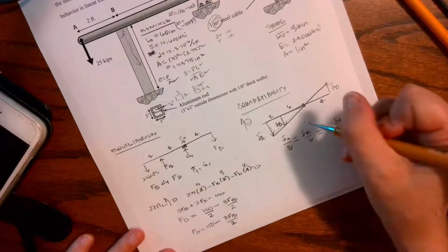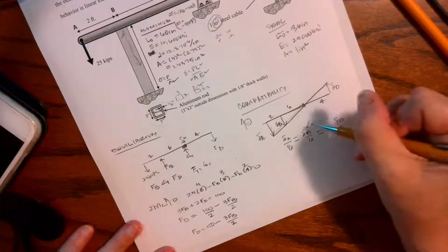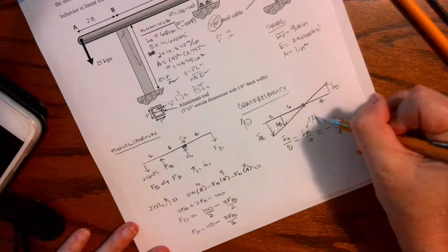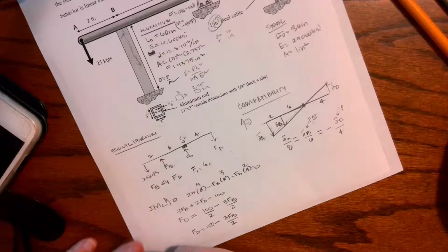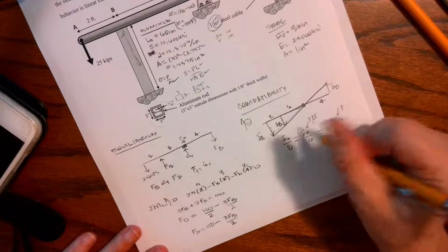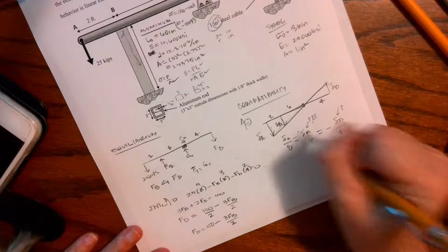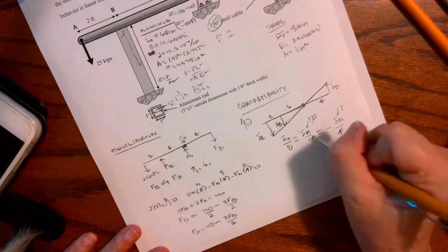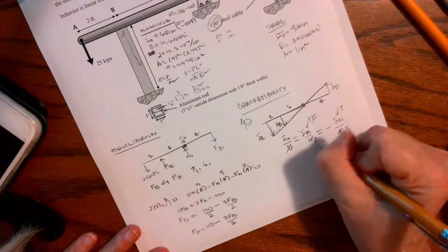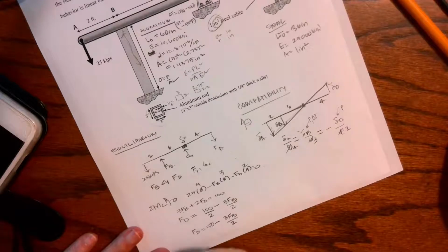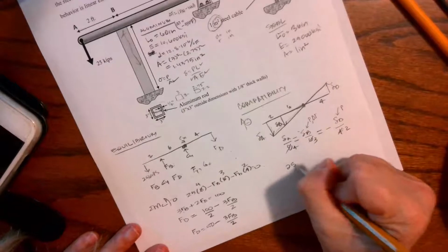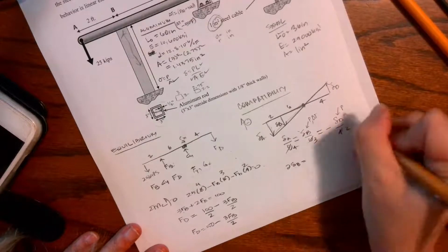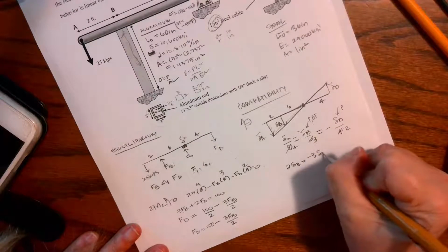When I know about deltas, it's a function of force and temperature change. We have force and temperature change on B, and we just have force on D. So I can start simplifying, and I can say, let's just get rid of a 2 here. So I've got a 2 and a 3 and a 4. Might as well, smaller numbers. So I have 2 delta B equals negative 3 delta D.